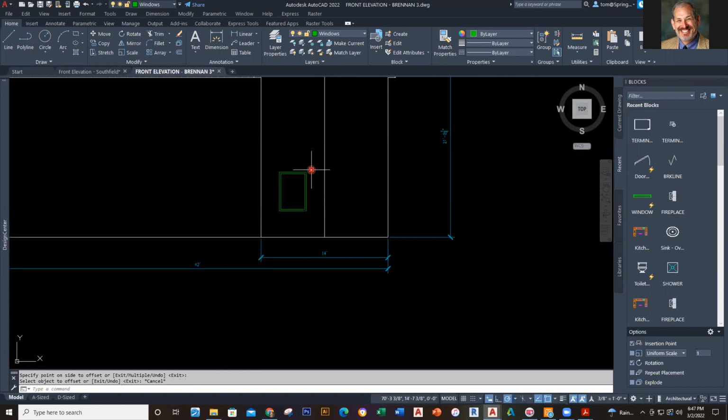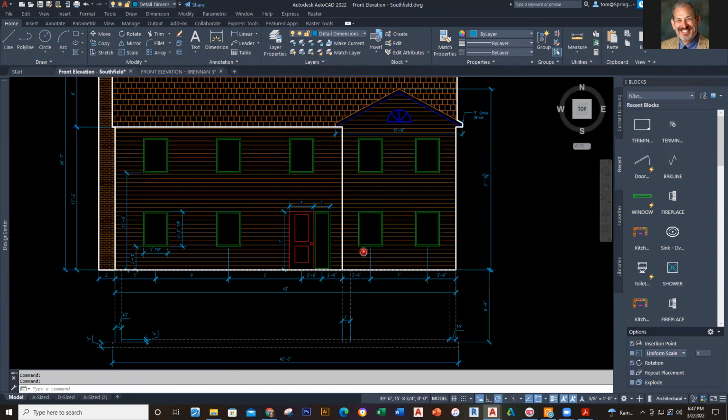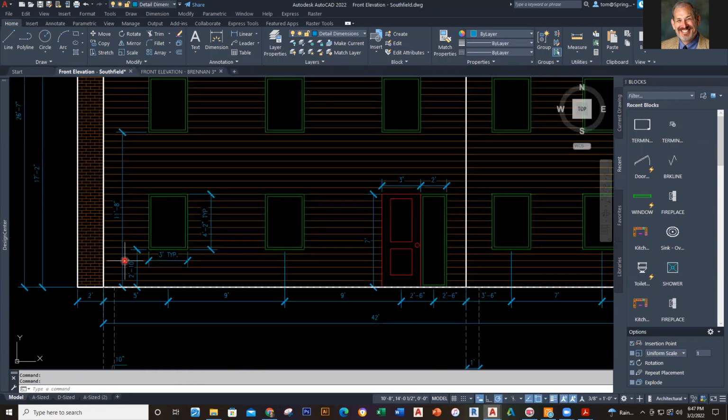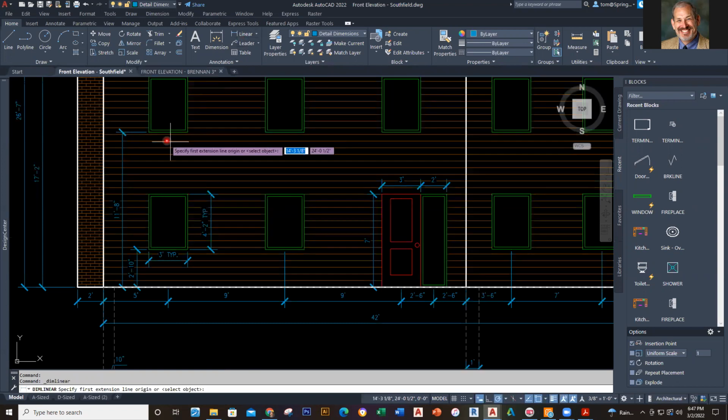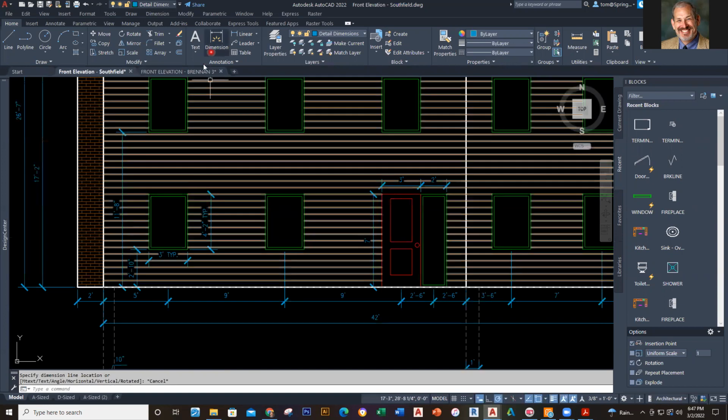And then at that point, I could actually begin to copy it over into the different locations. So I go to copy here, and I'll grab these. And this needs to go over from here 7 feet. So I'll just type in 7 feet, and that's already there. So those 2 are in place right there. And then the windows that are actually on the 2nd floor are supposed to be 11 foot 8 from the bottom. And so if I want to know the distance between these, I could just go from here to here, and that's 4 foot 8. That's good. 4 foot 8 is the distance.